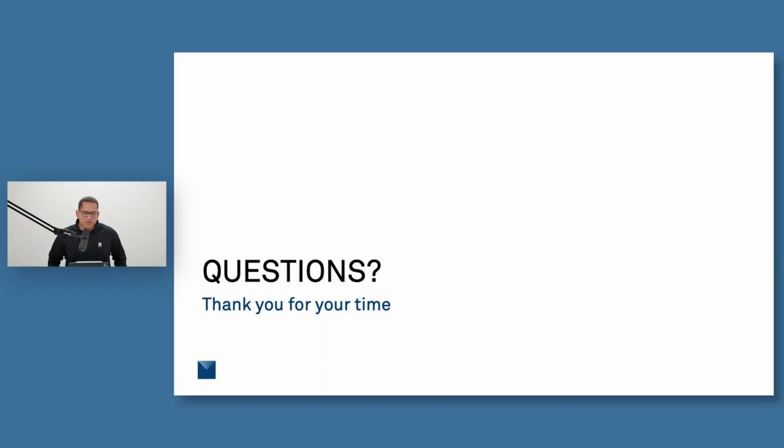Yeah, so that's a really good question, and is maybe leading for me because that's an area that we're working on. But there are differences, and this is well known that when you're infiltrating from the surface with something like the SATURO, you're measuring the water as it's moving through the whole profile. So as the wetting front moves through, depending on how deep that wetting front moves, it's that profile that's controlling it.